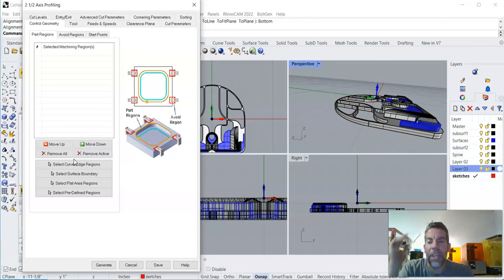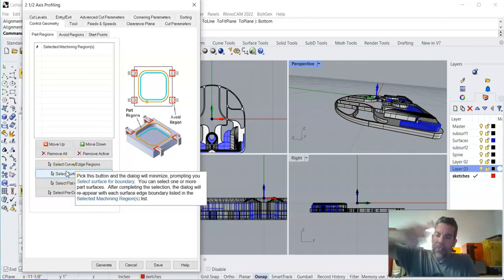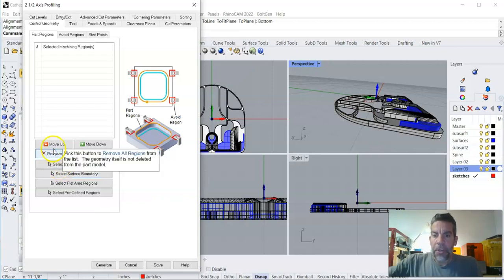3D geometry to be cutting 2D tool paths. Technically it's called 2.5 axis because your X and Y are moving simultaneously, but your Z is the half axis, and it's only moving between levels, up and down. So it's not moving while you're cutting in the X and Y, and that's why it's considered 2.5 axis.